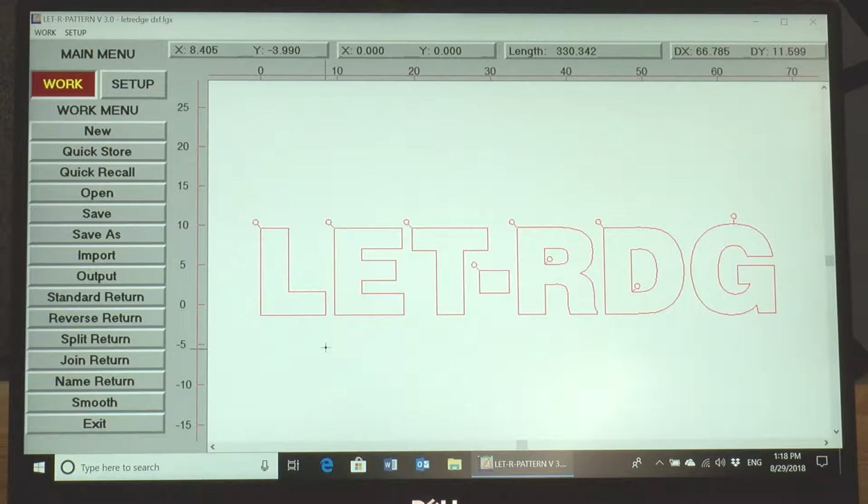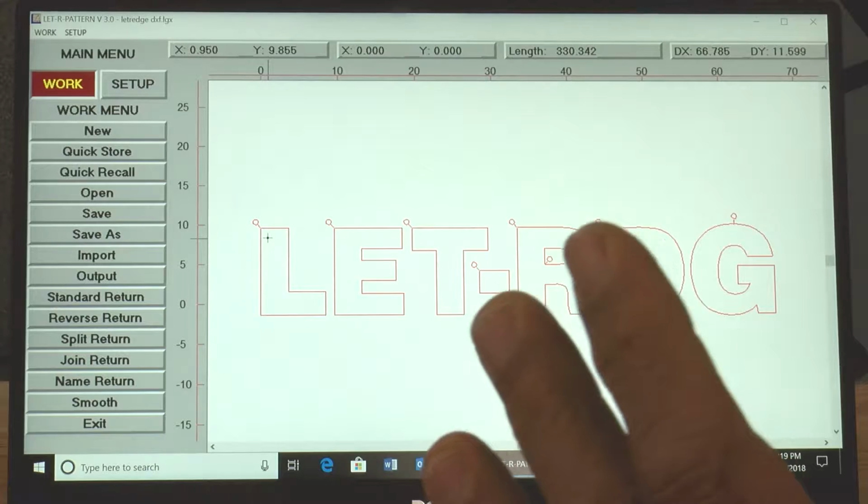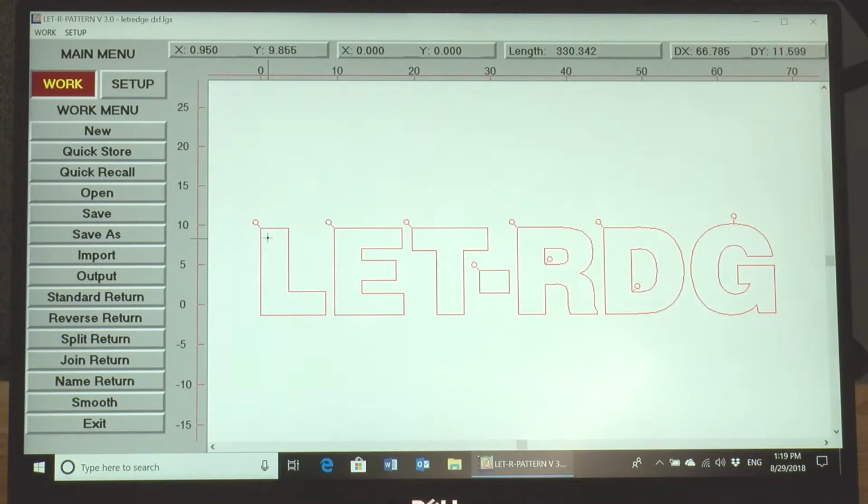Another interesting thing that you have to learn is that when you use the pattern printer software, you have a couple of options. It's not limited to the LetterEdge product. Somebody can actually use it for regular aluminum letters, and even for welded letters. If you're doing flat aluminum on LetterEdge, it typically goes outside of the shape. Either LetterEdge is glued directly to the plastic, or if you do it with flat aluminum, you form the letter and then you have a trim cap around it.